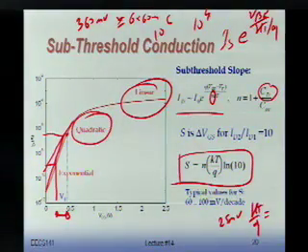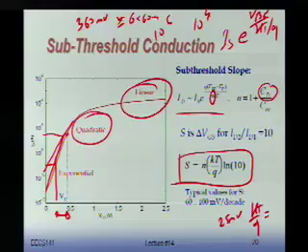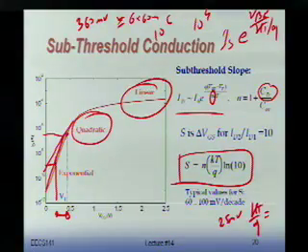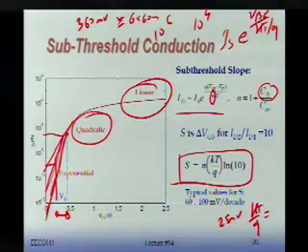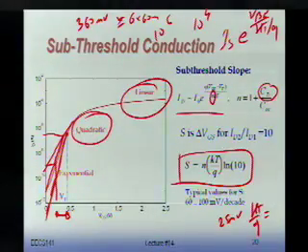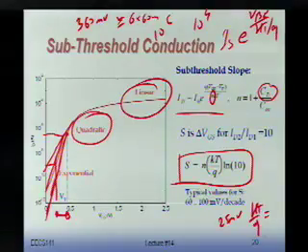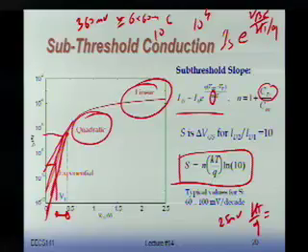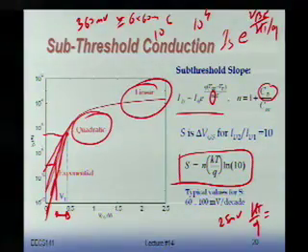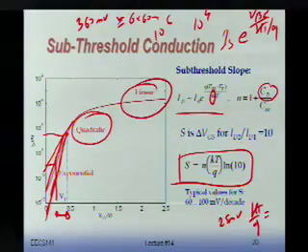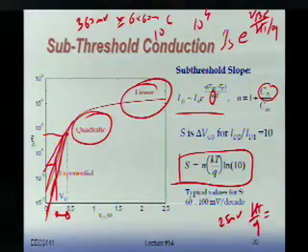So there's a lot of people working on this today. If you go to some of the universities, like here in Berkeley, and you go to MIT and things like that, a lot of people are trying to make transistors that have a steeper slope here. How can I make this slope as steep as possible? If I can make it steeper than 60 millivolt, boy, that would be really cool. Some people say it's impossible, but then people have come up with new device structures where they got lower than 60 millivolt per decade. I really would like to have a switch like this, right? It goes off and, bingo, it's off. You would like to have that. Will never happen, but we're all trying. That's what research is all about. Go for the impossible. Good.